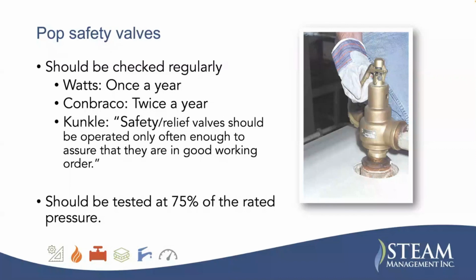So how often should you test it? Watts recommends once a year. Combraco, which is Apollo, recommends twice a year. And Kunkel says safety relief valves should be operated only often enough to assure that they are in good working order. I have no idea what that means, and I don't think it was an engineer that wrote that. I think it was a lawyer that said, "Okay, we're going to put this on there and this should take care of it."